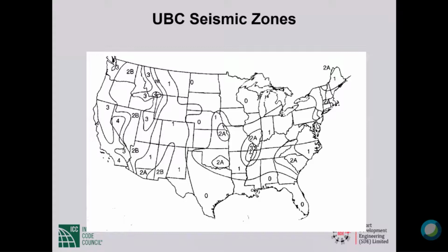special shear walls could not be more than 160 feet tall. The level of analysis we had to do as the basis of design depended on the seismic zone in which a structure was located. A structure in zone 4 in many situations had to be designed based on dynamic analysis rather than equivalent static analysis. So the level of detailing, the height limit, the analysis we had to do, all those important decisions depended solely on the seismic zone in which a structure is located.